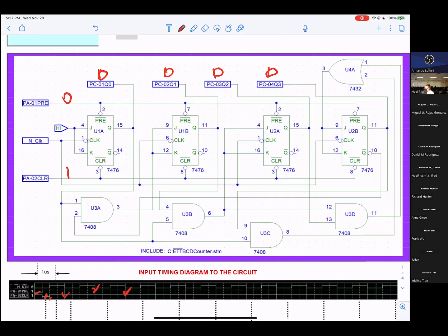Okay. If you understand, then you can do it this way, using the meter to measure E1 pin 2, pin 7, E2 pin 2, and E2 pin 7. They have to be 0. That means they can be any voltage less than 0.8 volt.